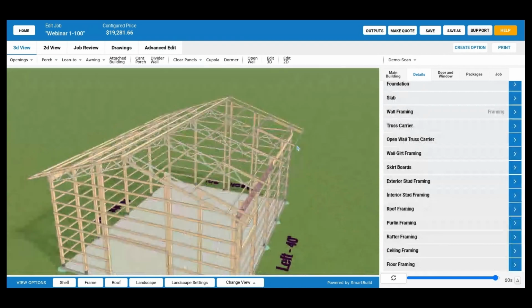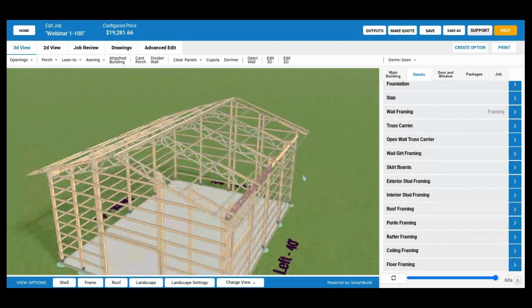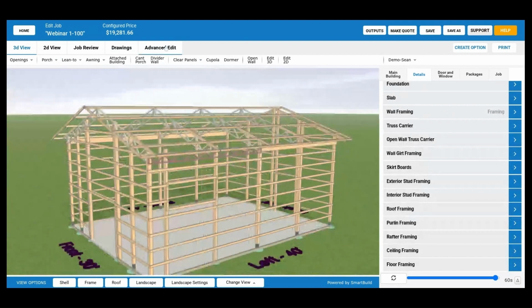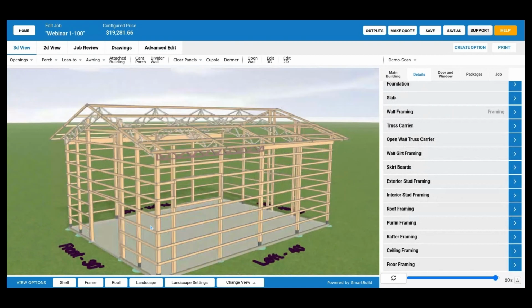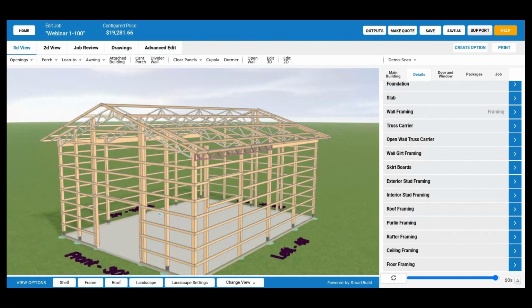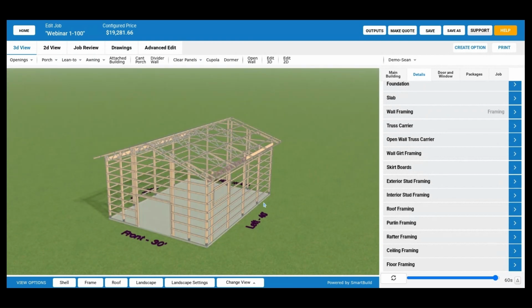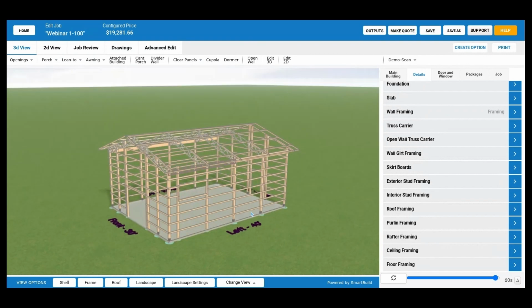And one thing to note on all these things that we've been talking about, just to give you some more power and more control, is you can go into advanced edit and you can override pretty much anything that we've been talking about here, even the structural, non-structural openings, even post-assembly materials and different things, in the advanced edit per wall and even per opening. So you could potentially have structural and non-structural openings for different openings on individual walls, or you can override this for all walls.